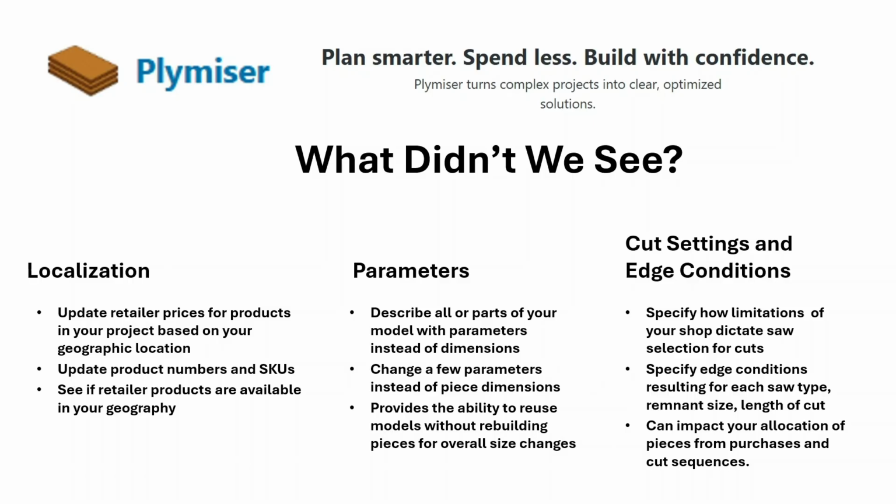It's got a general purpose blade on it, and it doesn't give me a good cut on plywood, especially on cross cuts. So I like to leave an extra 1/4 inch dimension on these pieces when I break them down, so I could trim them down in my basement on my table saw with a fine tooth blade.